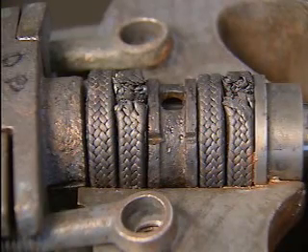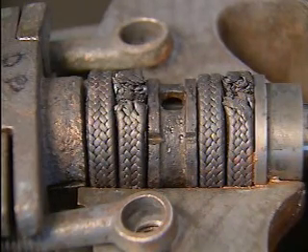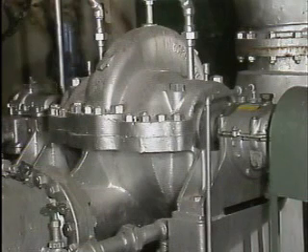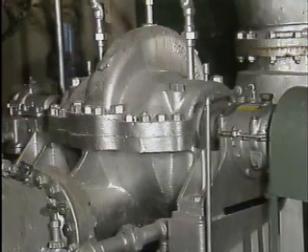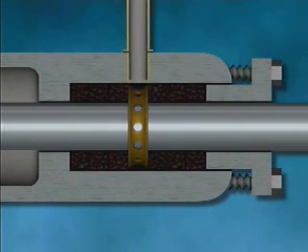On this pump, a metal ring called a lantern ring is installed between two of the rings of packing. The lantern ring provides a means for bringing more liquid into the stuffing box to help cool the packing. Certain applications, such as pumps, generate more friction than others and require this additional fluid to keep the heat that builds up under control. The lantern ring is always positioned under a line called the gland seal line.